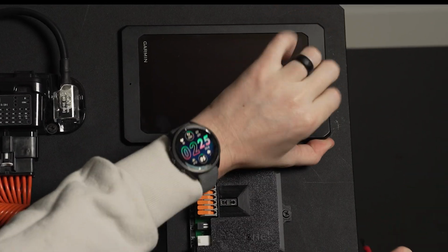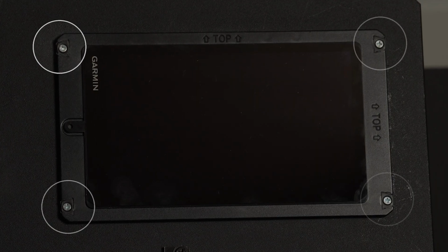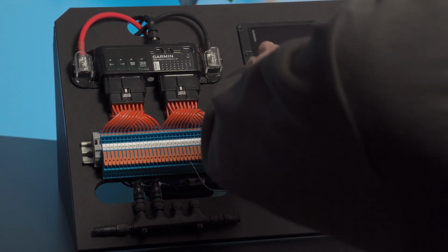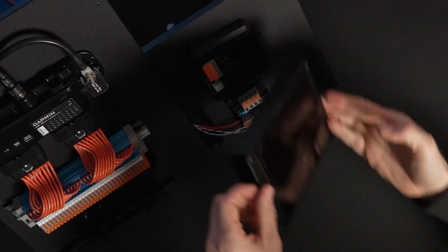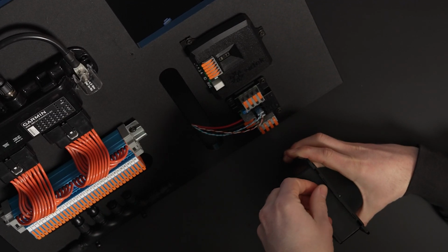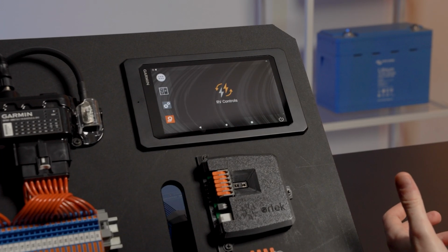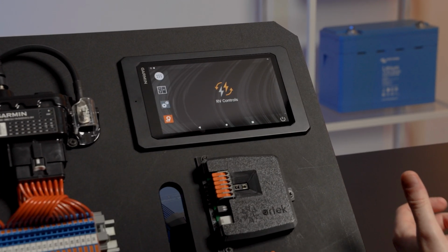To access the SD card, you'll remove the bezel on the front using a small screwdriver, remove the 4 screws and pull the screen out. In order to pull the screen forward and access the SD card, you might need to disconnect the plugs behind the screen first. Please be careful when doing this, as you can damage these quite easily. Once you've inserted the SD card, you'll need to make those connections again so that the screen can power back on for you to continue the process.